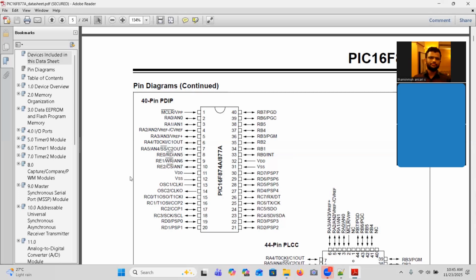When you do not have external clock circuitry and you want to use the internal clock circuitry of the microcontroller, you have to supply a crystal oscillator. So if you have a crystal oscillator, you have to connect one pin with 13 and another pin with 14, because it has 2 pins. When you connect that, it will act like a clock source right now.